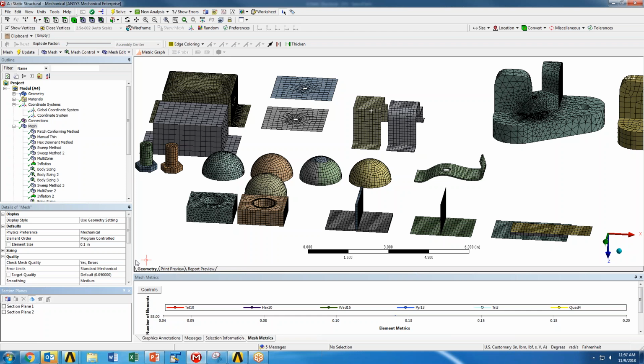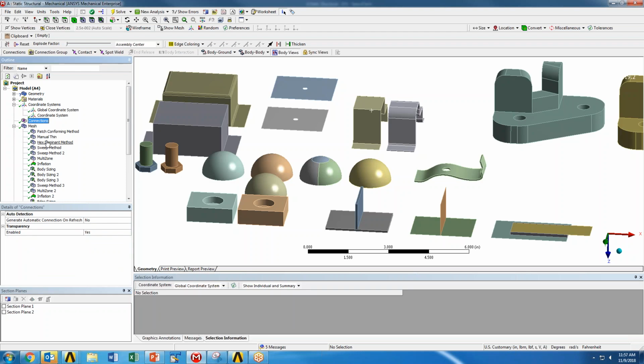And what that allows you to do is you're never going to get to the end of a large analysis where, let's say, you're only spending your time in SpaceClaim. You get to the end of reducing this huge assembly, and then you go to mesh it, and you find that the rules of thumb or the refinements that you're doing for every single part all of a sudden didn't achieve what you wanted, right? By doing the more iterative approach between SpaceClaim and Mechanical, you'll prevent that. And by doing your reduction in SpaceClaim, it's just going to make the process a lot quicker. Use shared topology heavily. That's going to reduce the need for connections, right? Anytime we reduce those number of connections, it's beneficial. And those are probably the biggest recommendations I can make.